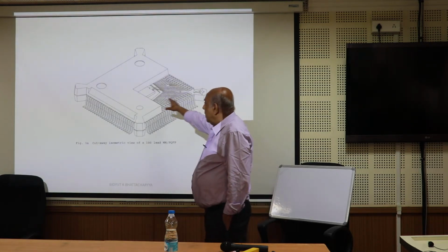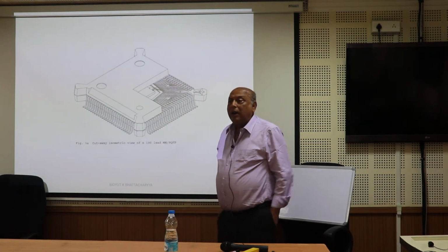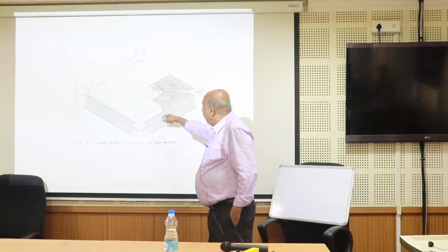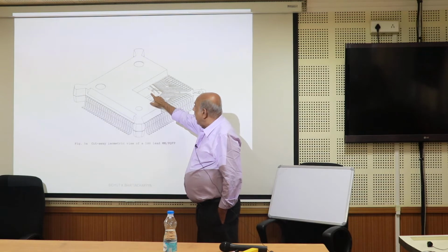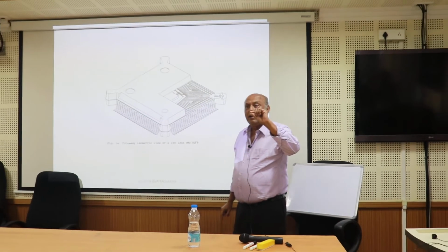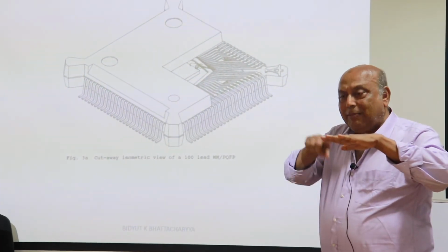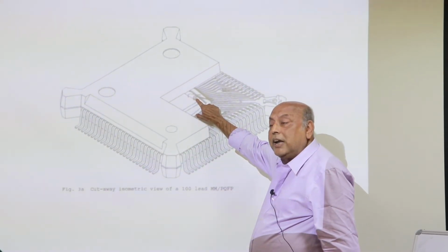So this is the package, 100 pin, 196 pin count packages I built. They call it Goldwing lead frame. And this is the silicon chip. I wire bonded them. Silicon chip is about 0.5 mil, about 100 micron. So when I bonded them right near the plane, right here, it is only 100 micron.